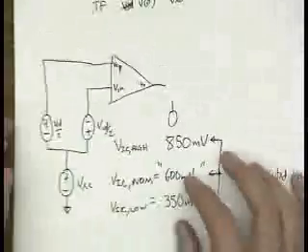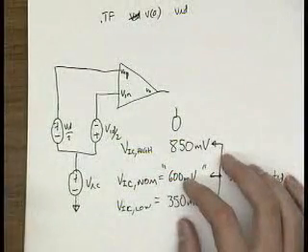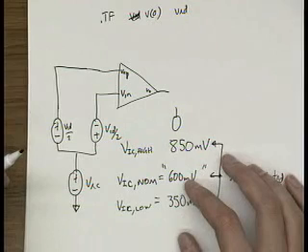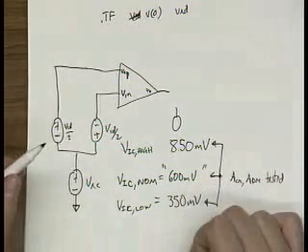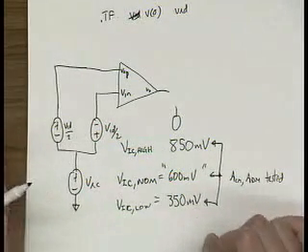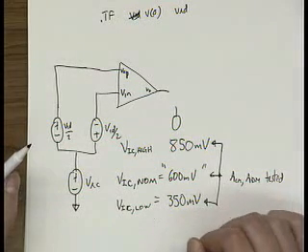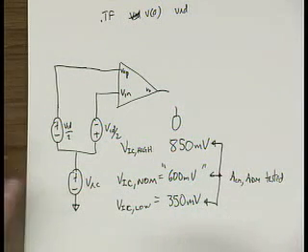Questions? Yes. So does that mean like when we test the VIC with the high value and low value, the differential mode gain will have to be greater than 1,000, and do they have to be approximately equal, or no? We removed the equality spec, so you could hypothetically design a very high gain amplifier where when you move the common mode up a little bit or down a little bit, all of a sudden the gain drops in half.